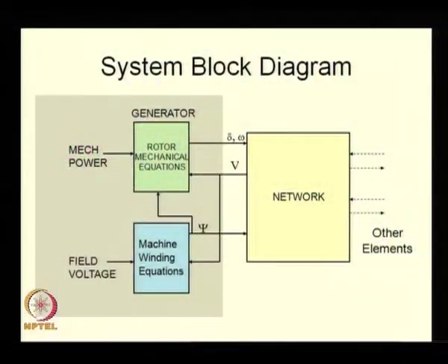Now, if you look at where we are right now, we have done the synchronous generator modeling, in which we have the rotor mechanical equations and the machine flux equations. They are differential equations in the fluxes of the machine, and the rotor mechanical equations are generally formulated in terms of delta and omega. Given the rotor angle, the mechanical speed and the fluxes, one interacts with the network.